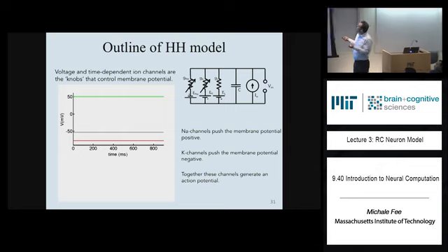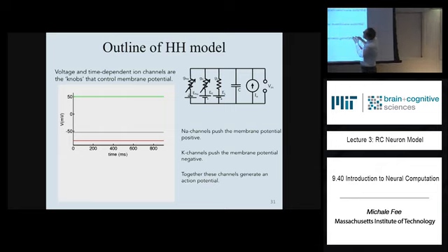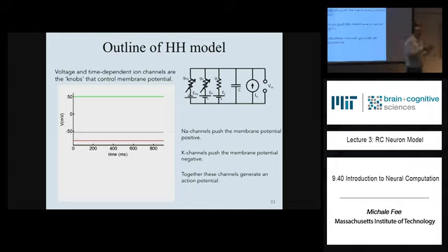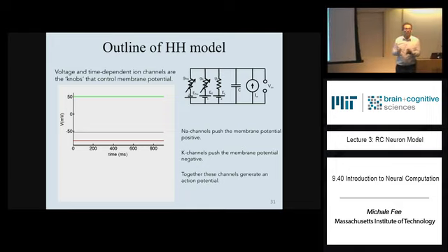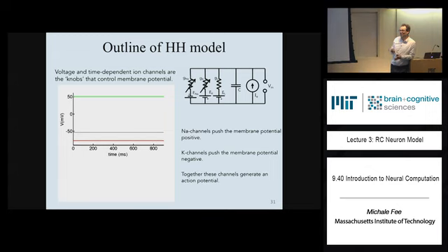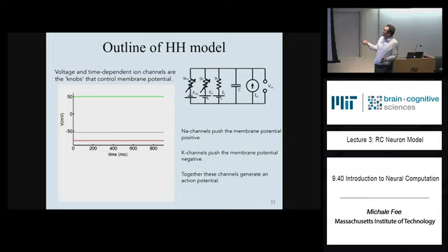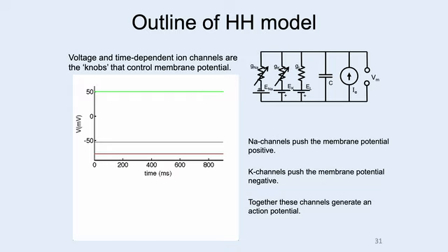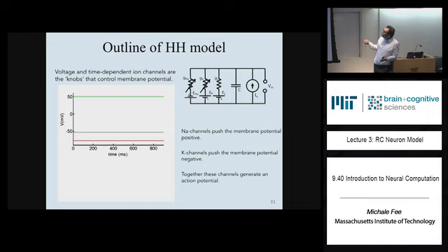So now, what happens if we suddenly turn on a conductance? What do I mean by turn on a conductance? We make the resistance really small, or we make the conductance really big, right? So what are we doing? Let's turn that conductance on as much as possible, which means we're setting that resistor to 0. If this resistance is 0, then the voltage drop across it is 0, and the voltage inside has to be set to the voltage of that battery. Does that make sense?